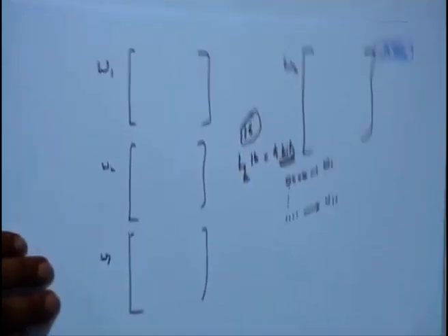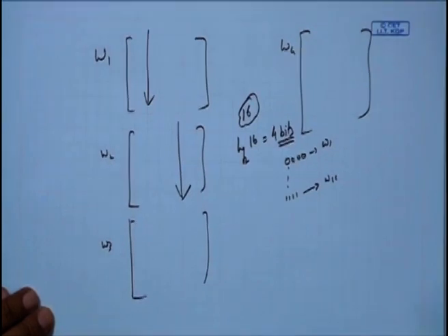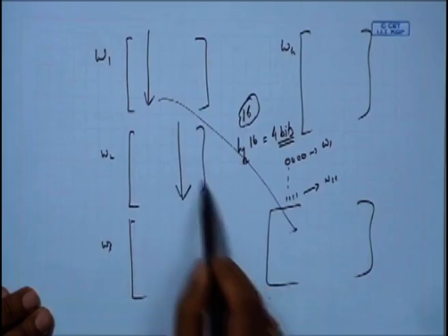Whereas in LTE, by virtue of having code books, it is still possible to multiplex users, so that in a fashion, for instance, one could choose different columns of these different matrices and form one new matrix which is using columns from different users in such a way that the different users' data or streams do not interfere with each other. And in this way, when the signal is transmitted to the users, users would have almost interference free communication.